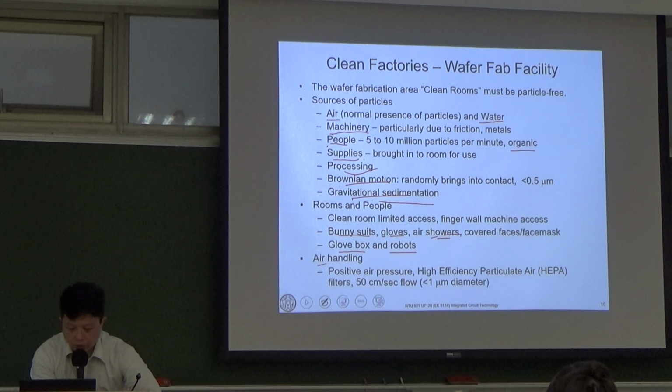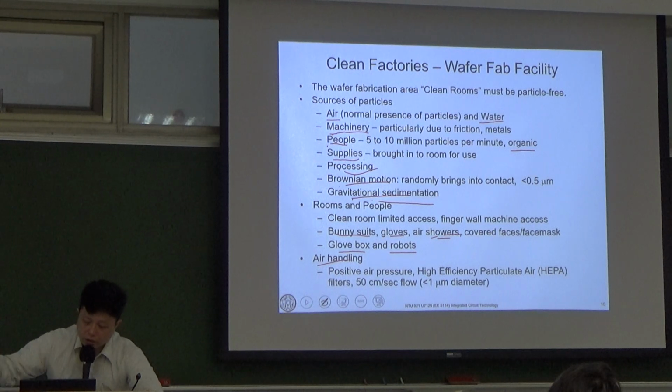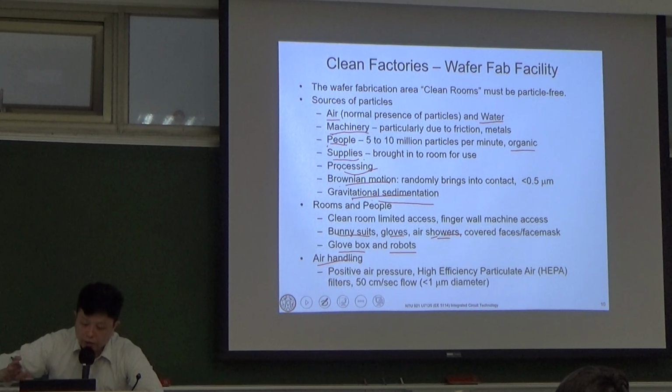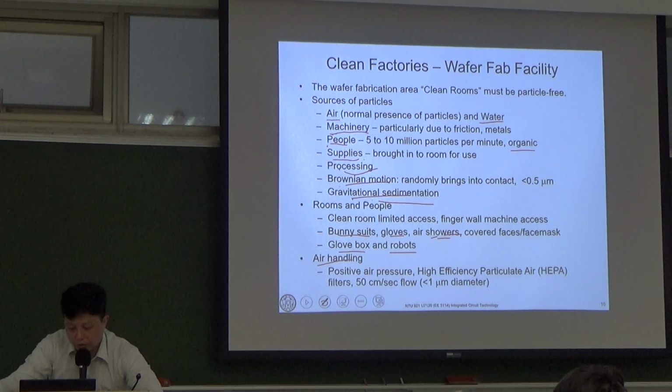Air handling is also very important. We have to maintain positive air pressure because we don't want the outside dirt particles to flow into the clean room. So inside the clean room, we need that positive air pressure. Once you open the door, it's clean air going out, but not dirty air coming in.